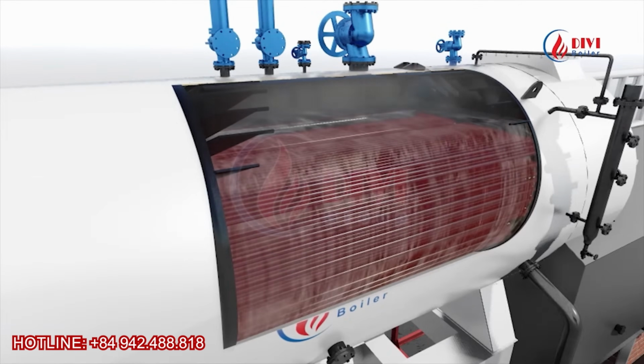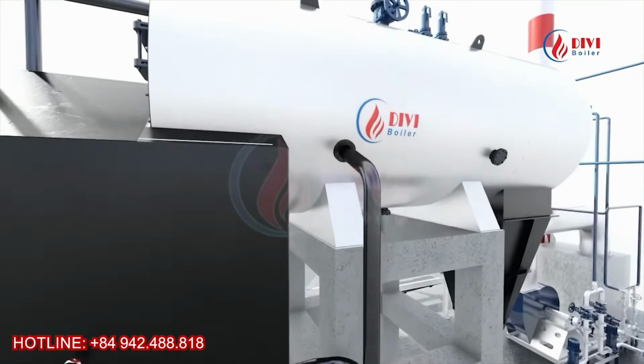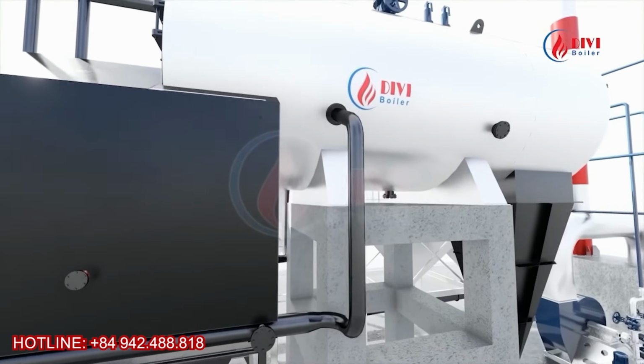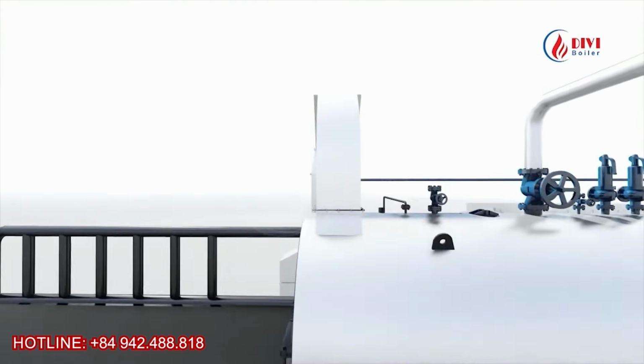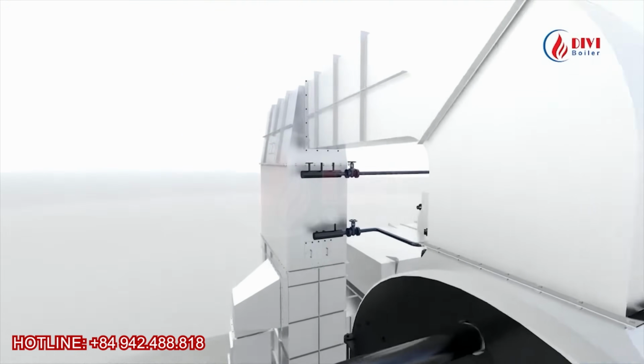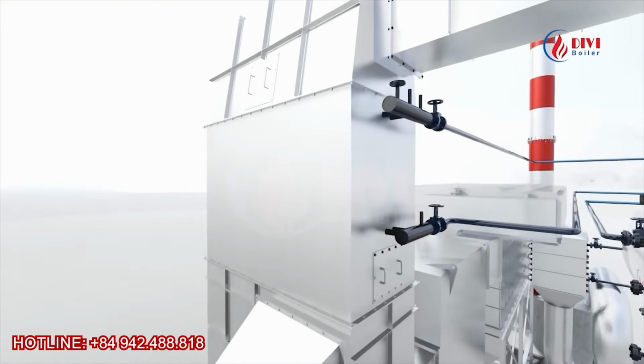Another feature of this design is its relatively large water storage volume, thanks to its large steam drum. The larger water volume means a longer startup time, because more energy is required to heat the water before steam can be produced. However, once the boiler reaches stable operation, it can maintain steam pressure more steadily, even when the steam load changes.